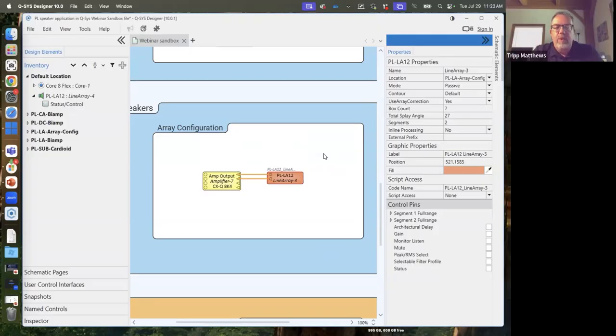I don't have quantitative information that tells me how much more improvement you get. You do get a lot more control over the array for your tuning, as your high frequency and your LF midband are easier to tune themselves, as opposed to having the dependency on our voicing algorithms to do that. But obviously you're bypassing the crossover inside of the box, so you can run the drivers a bit higher. I would have to look into that with engineering and get back to you, because I don't have any personal knowledge of running it.